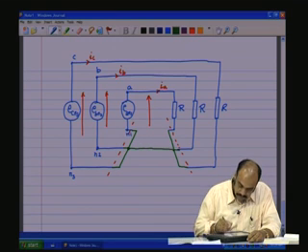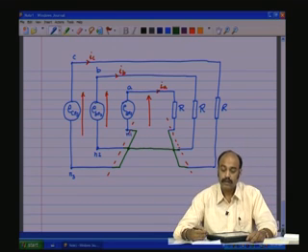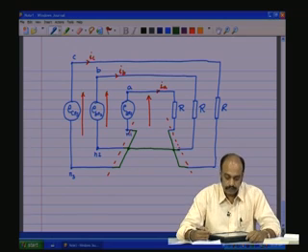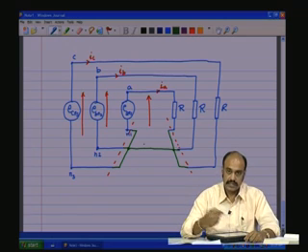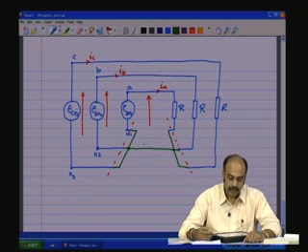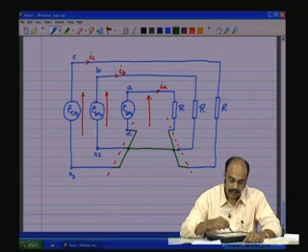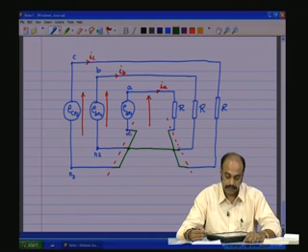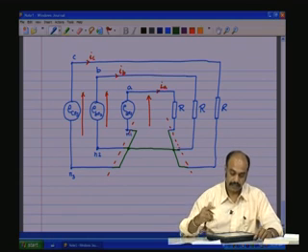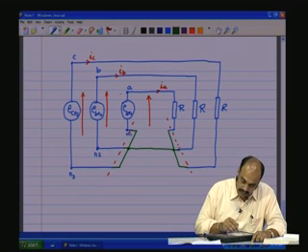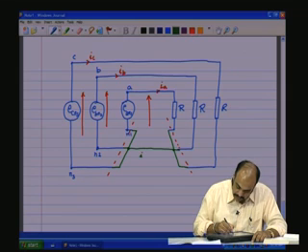And join them. So, what have we done? The 6 wire system has now become 1, 2, 3 and a 4 wire system. From a 6 wire system, it has been reduced and made more compact into a 4 wire system, and of course, IA, IB, IC is going to flow here. IA plus IB plus IC will flow here.